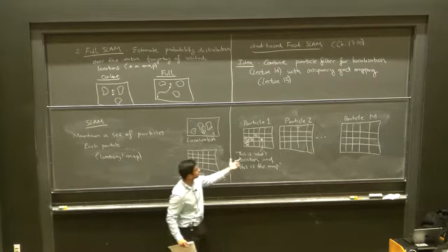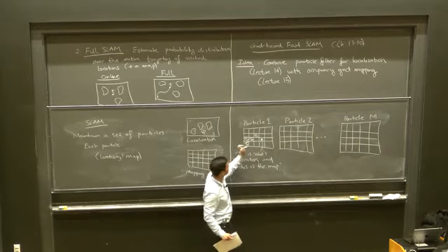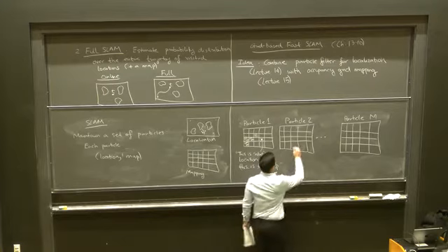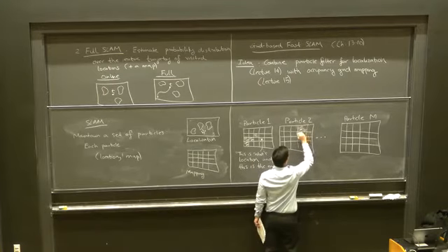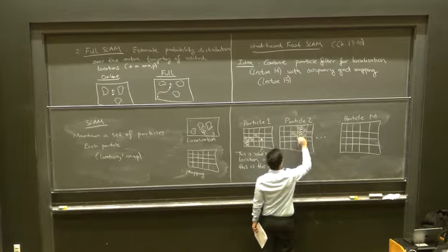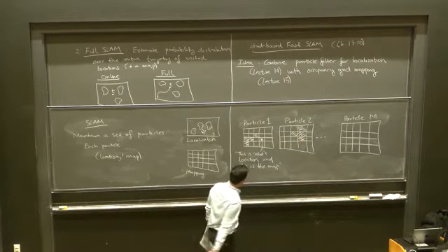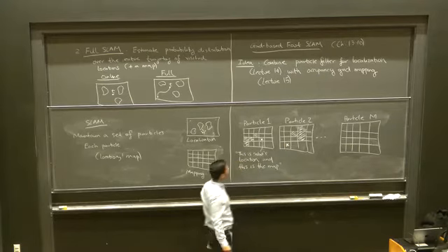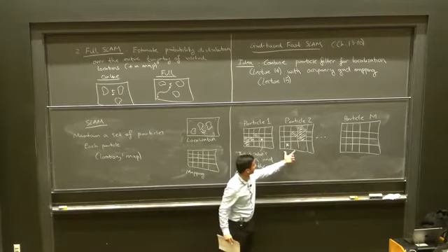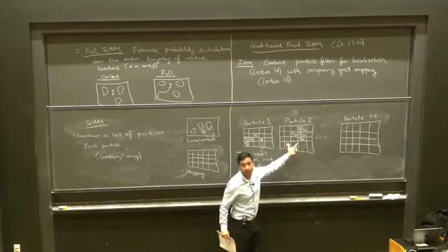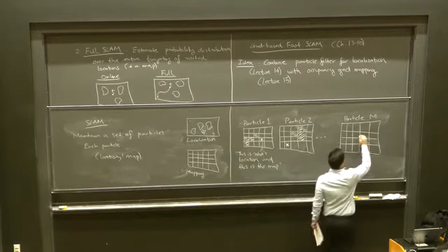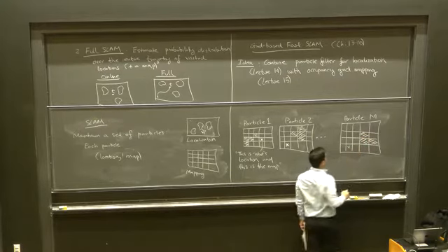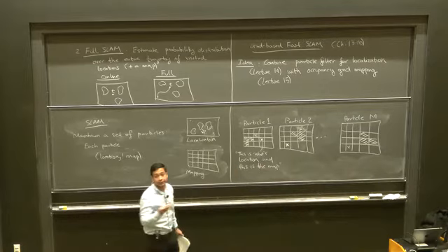So this is one specific hypothesis, right? One point estimate about the robot's location and the map. So with the particle filter, we're going to maintain a bunch of these. So let's say this is the location estimate. This is another particle corresponding to a particular location and a particular map, and so on. We're going to have capital M of these pairs of location and map.